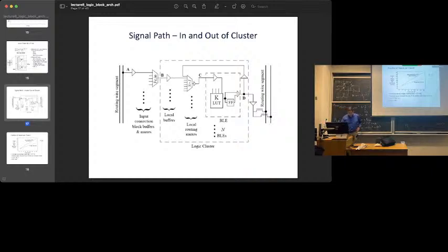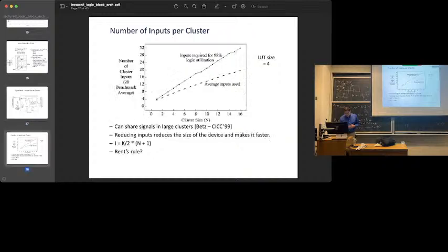So what they did is they looked at the output of the packing stage, the stage that's actually making the logic blocks across their benchmark circuits, and they varied it. This is work from a paper to reference. They're working out how many inputs they need in order to be able to use almost all the lookup tables.